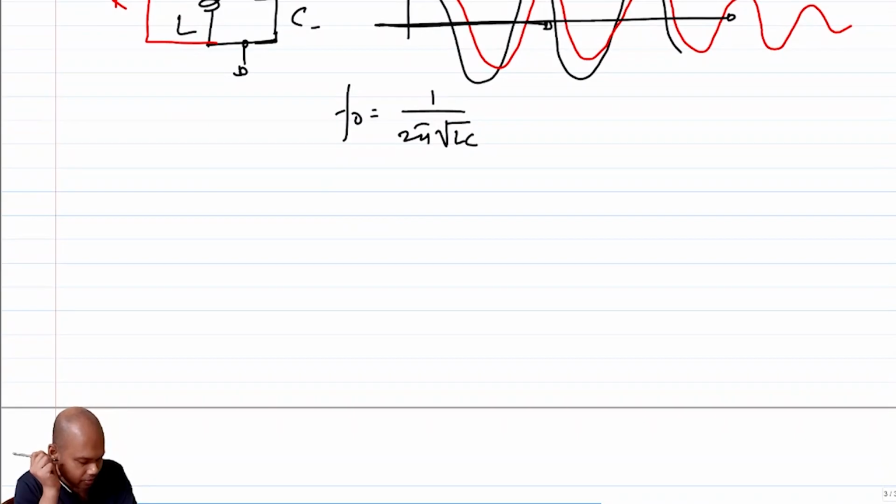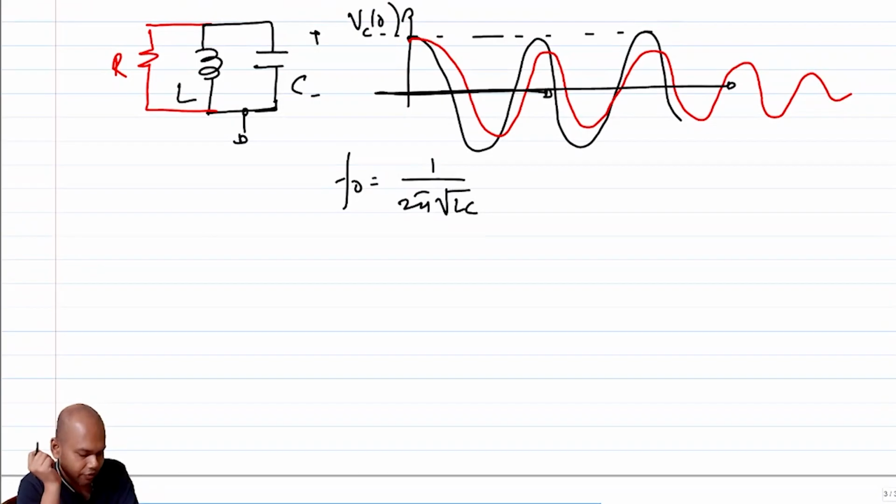The solution, in a very mathematical sense, is that if I have a lossy element R, which is taking away energy from the tank, then I should have a generative element which can push energy into the tank, right? So if R, or G as in the conductance, gives me loss, then if I am able to put another negative of G in parallel to this RLC contraption, then I should be able to negate that loss, right? So that's all that theory is telling us.